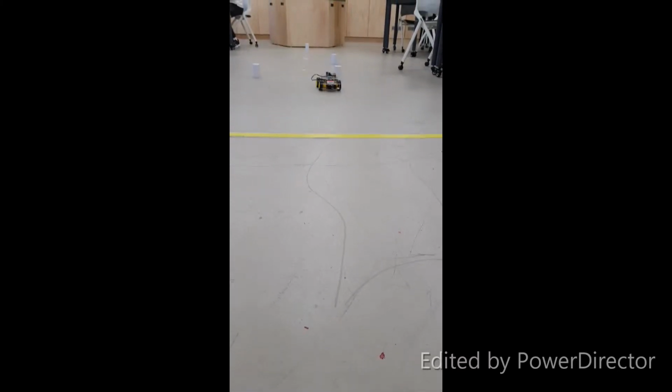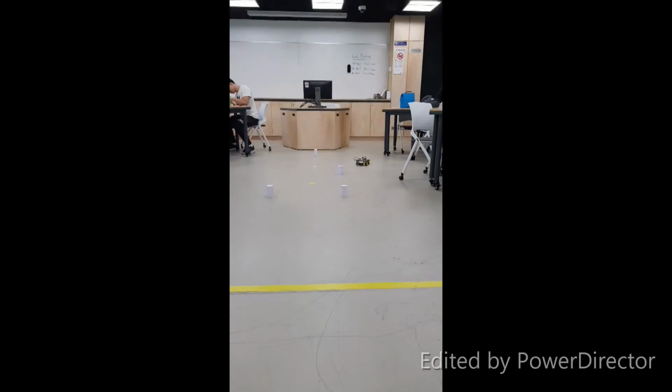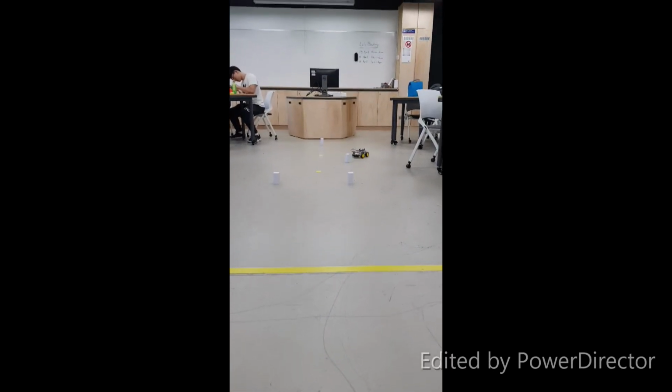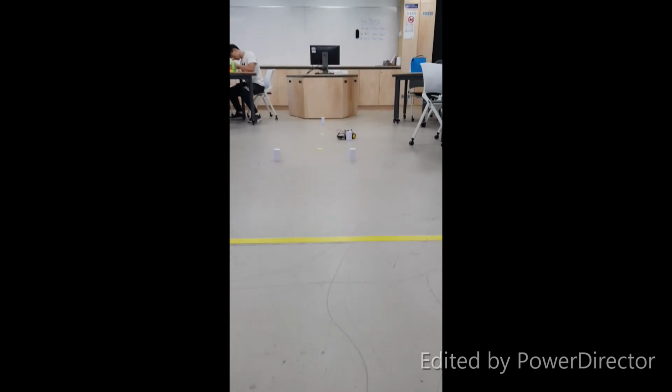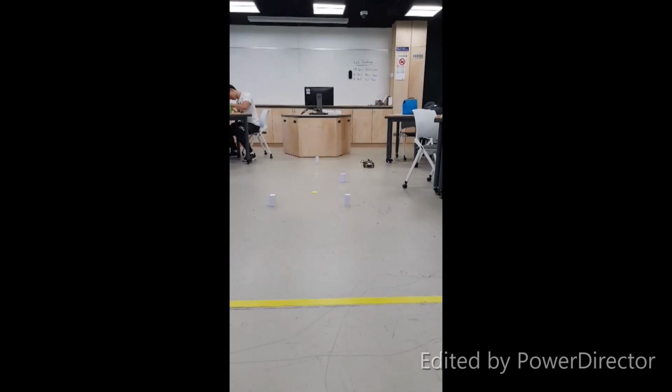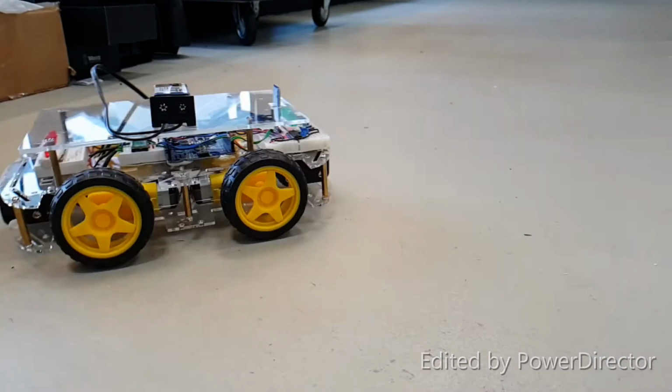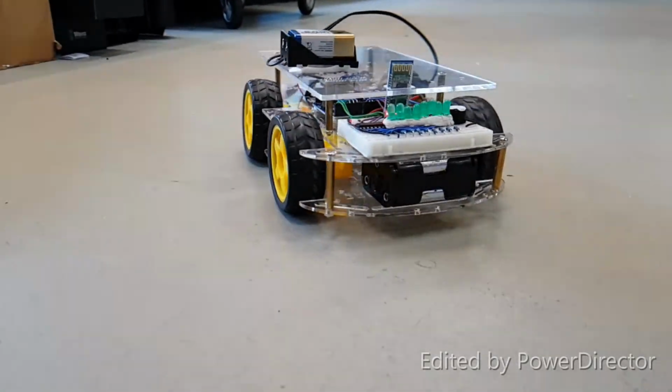The second difficulty is, the curvature of the turns was not sharp enough when the robot is moving at full speed. You can see it in the video, the turns are much more responsive at low speeds. The problem is that the maker's lab floor is too rough and the momentum of the robot is not allowing the wheels of one side of the robot to stop moving when doing sharp turns. We overcome this by giving some reverse thrust to one side of the wheels so that it will stop moving during sharp turns.